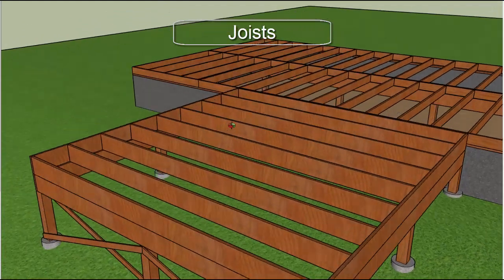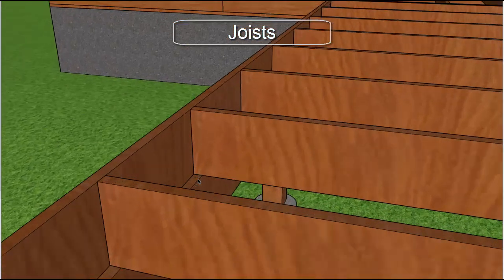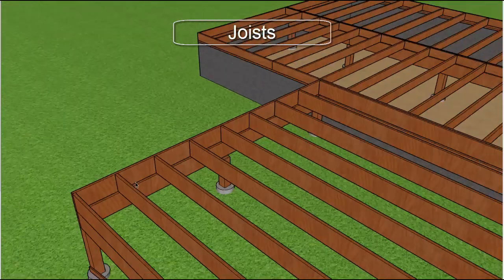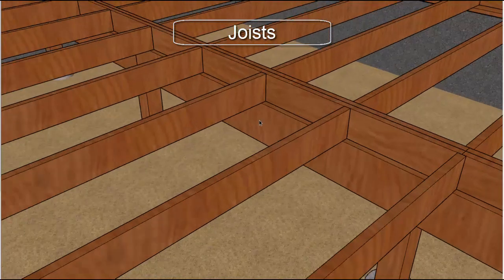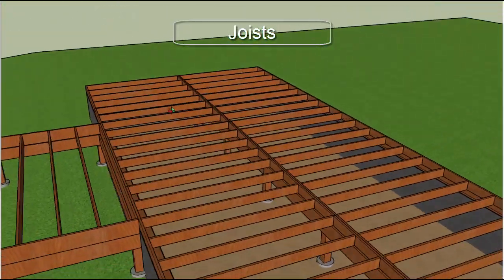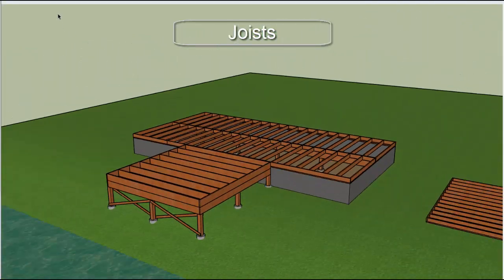Another thing to remember with floor joists is, just like the girders and the built-up sill, you have to have bearing. So that floor joist must be resting on the sill or on the girder, unless you are using some sort of commercial metal joist hanger or fastener.